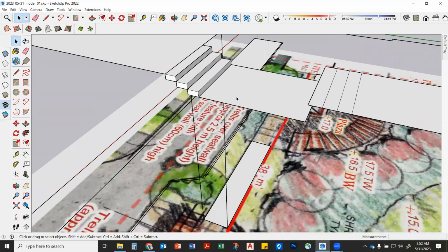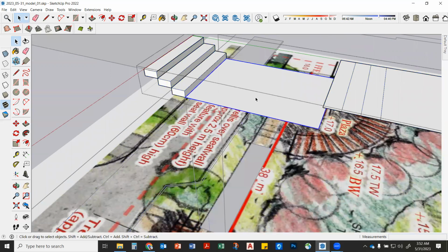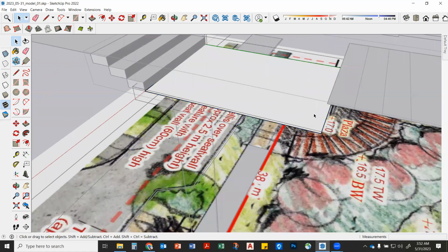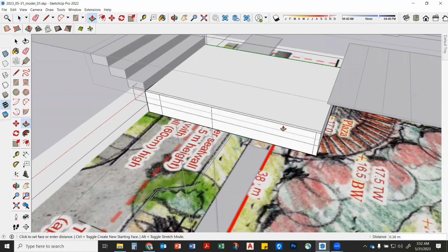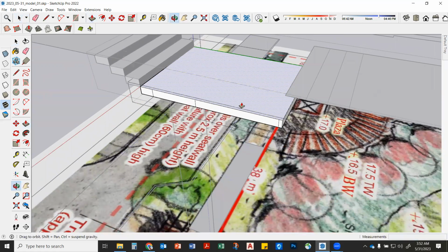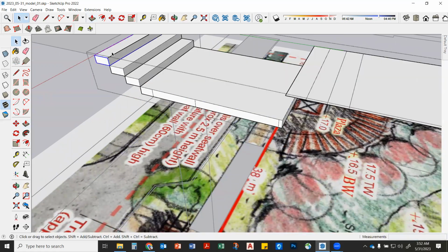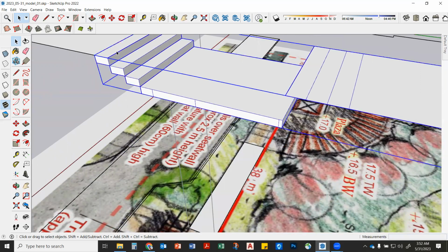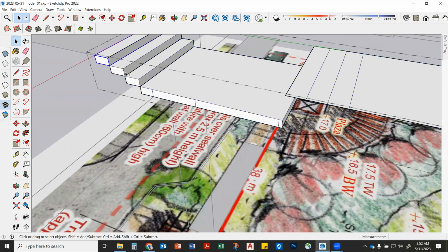We've got 3 right here, but we're just going to make this the thickness of a riser too, right? So we're going to come here, push, pull on this guy. Oops. I need to be inside this little group I just made. Push, drop that down 0.15. Enter. Okay. So now that has some thickness. Then I can grab these guys, 1, 2, 3.